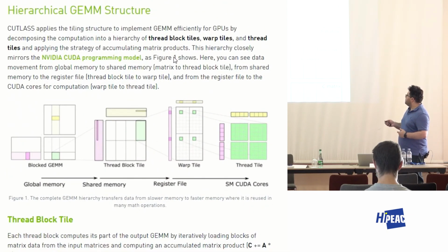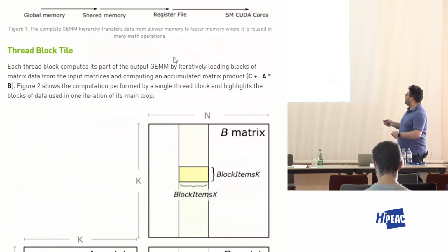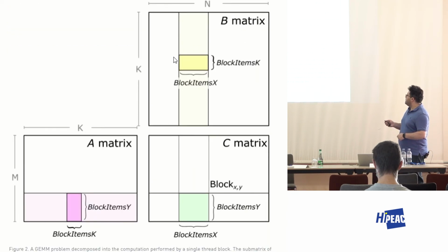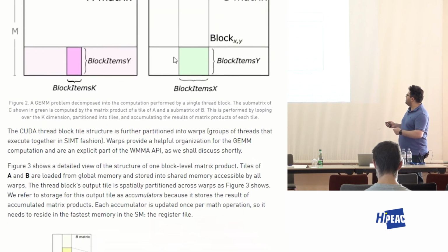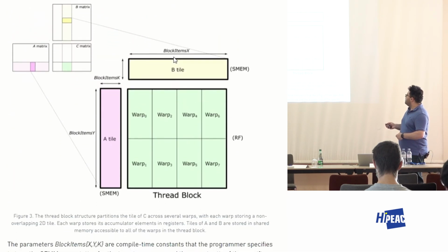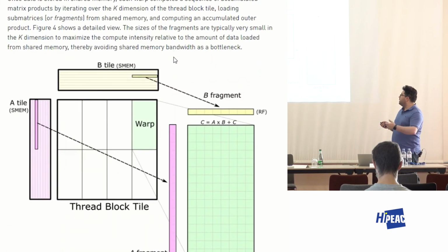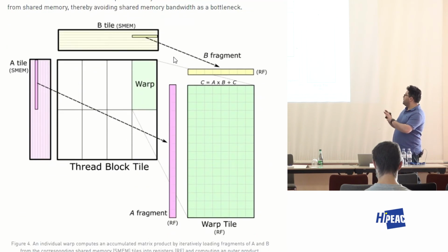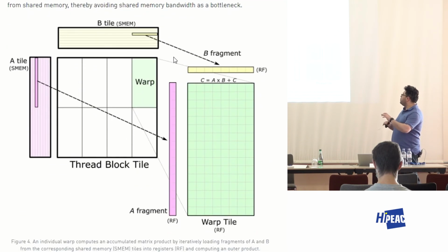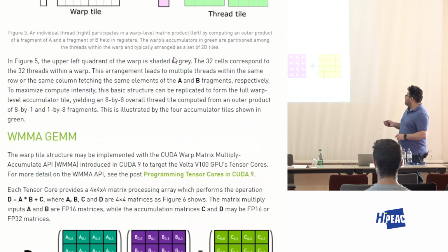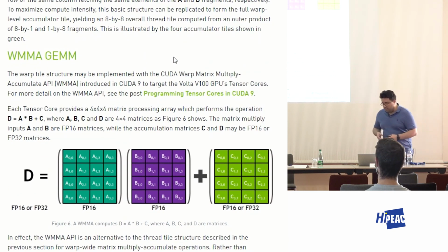consider these things. Okay, this should be coming to the shared memory, and then the memory comes to consideration. What should be the best combination of this thread block size, the number of warps, number of thread blocks, and these are the things that, for instance, we have different implementations in a library like this, depending on what is the size of the input and output matrix, and the output, it is very much faster than the naive implementation.